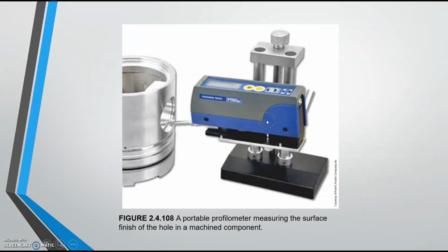Now, here's a cool tool. This is a profilometer, and what this is doing is measuring the surface finish of this hole. Now, this machine knows the surface profile, and what it's going to do is electronically move across the surface and determine the level to which the peaks and valleys vary from the original profile of the surface. And that will allow us to determine the average roughness, Ra, like we saw before, and make sure that it falls within specification.